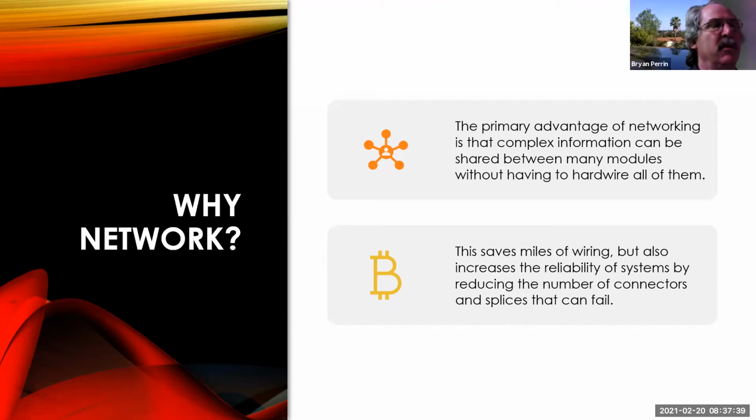So that's where we get it. We use the wheel speed example in the book, and modern vehicles don't use a vehicle speed sensor anymore. Why? Because I got 4 wheel speed sensors. So back to your question of redundancy, Daniel. I have redundant wheel speed sensors now. I got 4 of them. I don't have a redundant ABS module. That's what I mean. Some areas, yeah, I have great redundancy. I got 4 wheel speed sensors, so my speedometer is not going to drop out because I have one sensor go bad, which is what used to happen. But by the same token, if my ABS module goes out, I no longer have wheel speed.